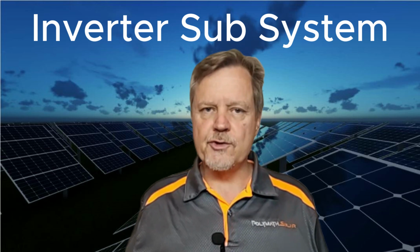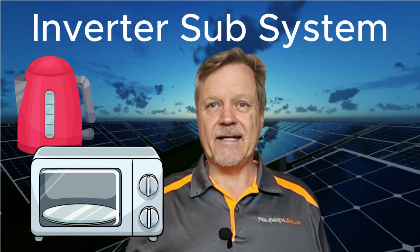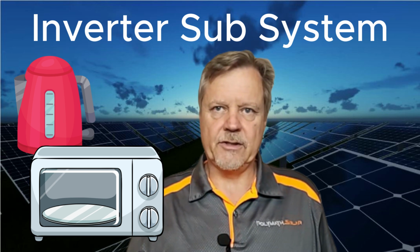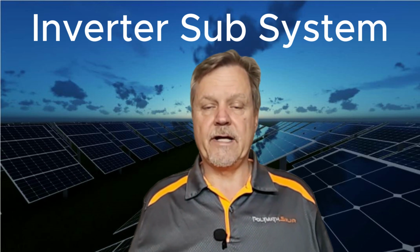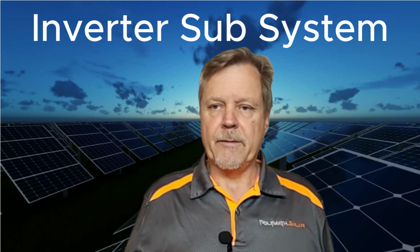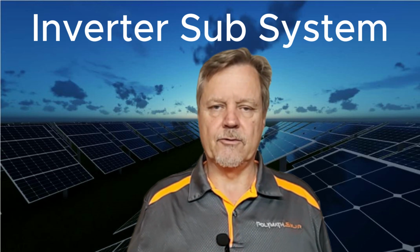What if the inverter is too small? Well, if the inverter is too small and you switch on the kettle or the microwave or whatever it is, and that item takes the inverter beyond its capacity, so let's say it's a 3 kilowatt inverter and the load that you're expecting from this inverter is 5 kilowatts, the inverter will shout, say, I can't do that, and the inverter will shut down. It's damaging, it's dangerous to do that with an inverter all the time. If you keep on overloading the inverter like that, the inverter will probably fail in due course.